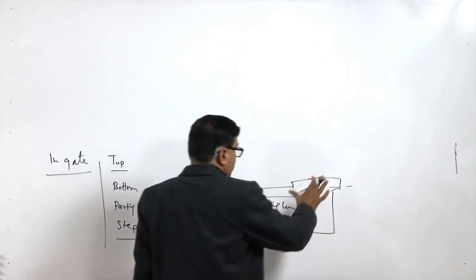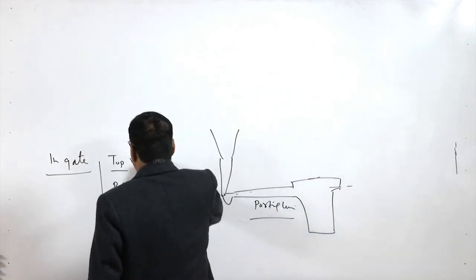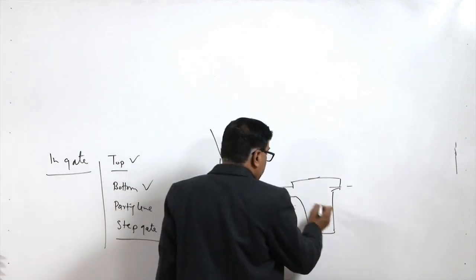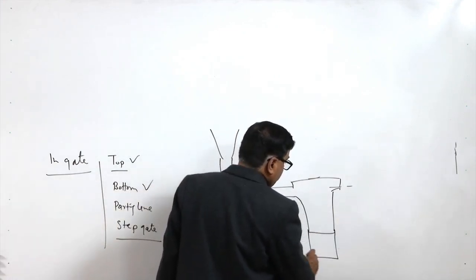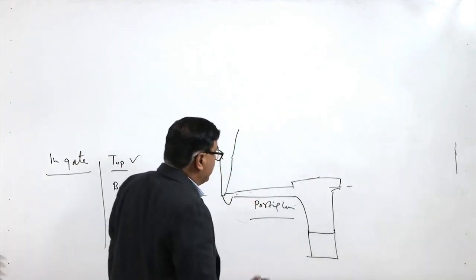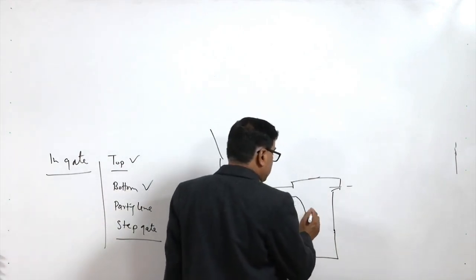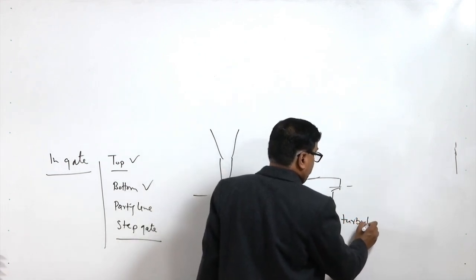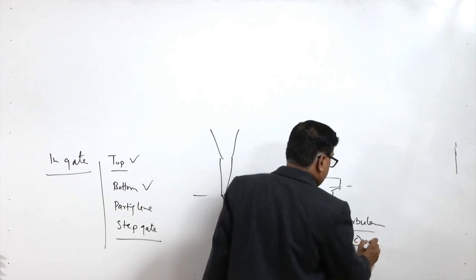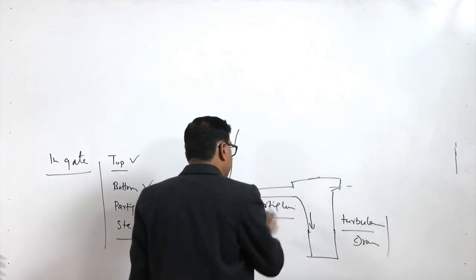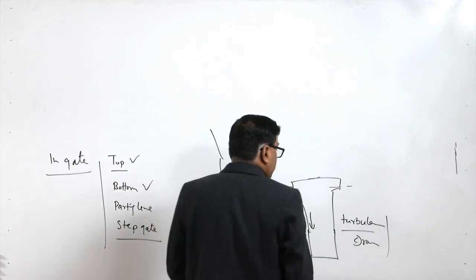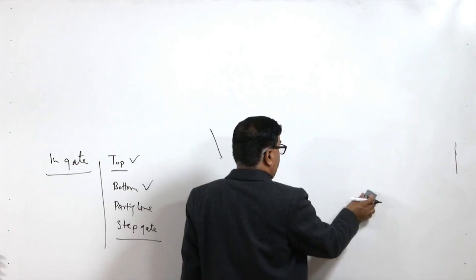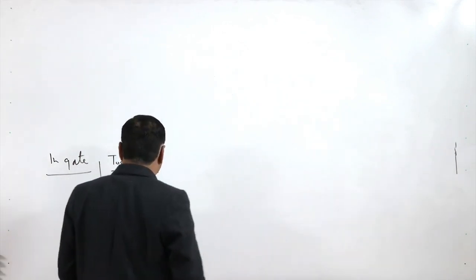This compromises between both the top and the bottom, and tries to have the benefits of both. But if the depth of the cavity in the drag is much higher, then again it causes turbulence and dross formation tendency. If the depth is shallow, the parting line gating system balances the turbulence and dross formation tendency in a better way.